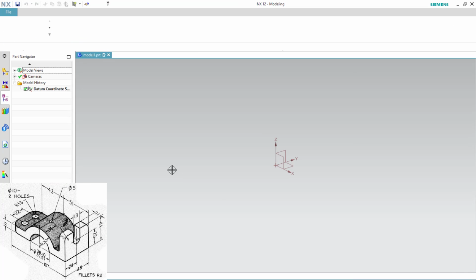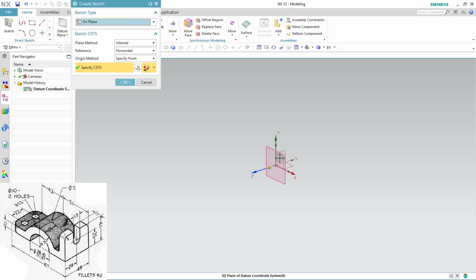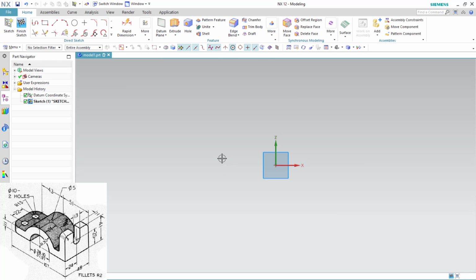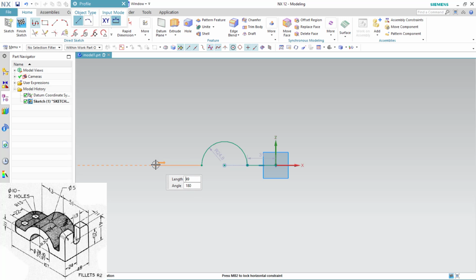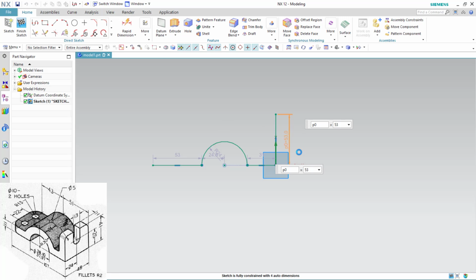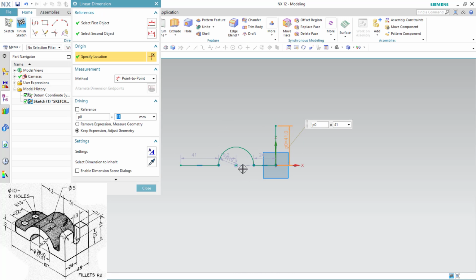So you could see this is the model. You can start with the workbench. I'll refer the front plane. You can draw the rough sketch. As you could see, if I consider the front side view, you'll get this sketch, right? Yep, so like this you can use, and you can directly switch to arc by using the arc tool there itself. So dimensioning, you can assign it.